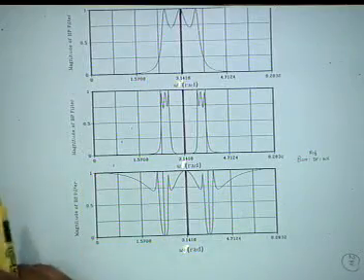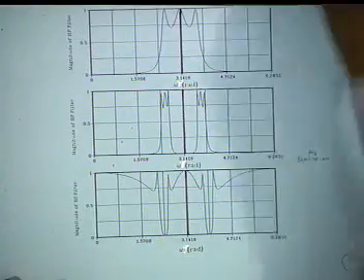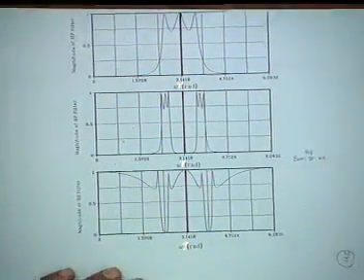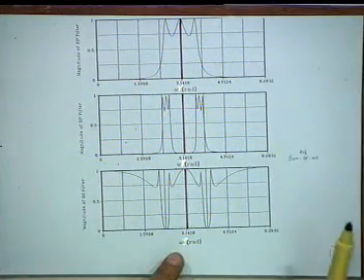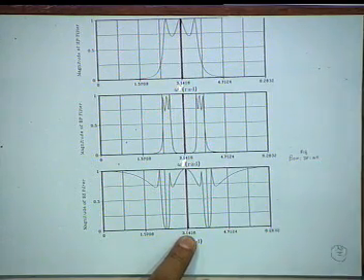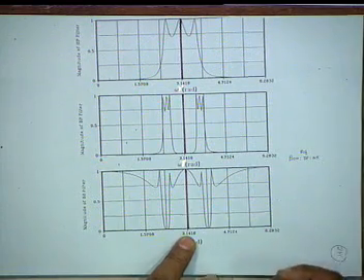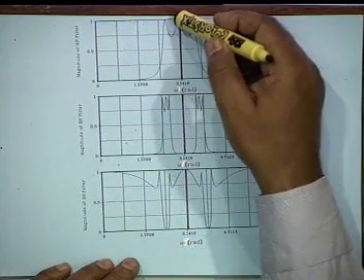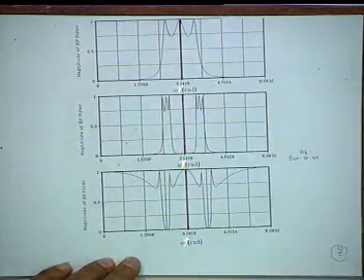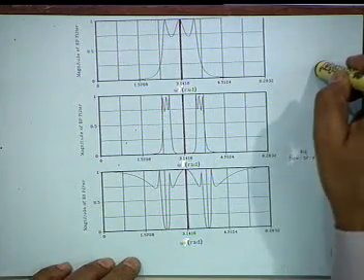That is correct. Now comes the question of their frequency responses. The three frequency responses are given here. A slightly peculiar way: you see, it is plotted not up to pi, but up to twice pi. Just to remind you that it is a periodic function and the magnitude is an even function. So what happens at pi on both sides, they should be identical. Again it will happen at pi, then 3 pi.